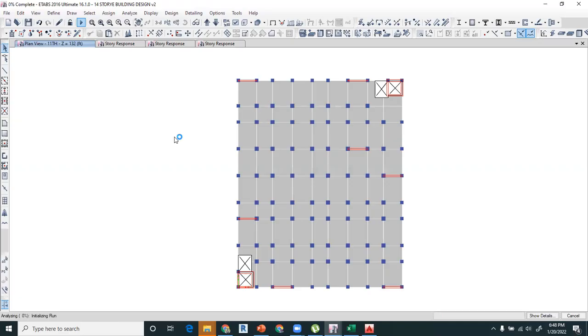Yes. So there is another. Sir, our drift story is up to the 7th story, so can we make our shear wall up to the 7th story? Also, how to save the economy? So you have to check the drift issue. For example, in our case, the maximum drift is at the fourth or fifth story. So you can provide your shear wall up to the fourth and fifth story, and you can ignore the remaining part, the 12th or 14th story. You don't have to move your shear wall up to the top. But if there is no restriction from the architect, you can also do that.